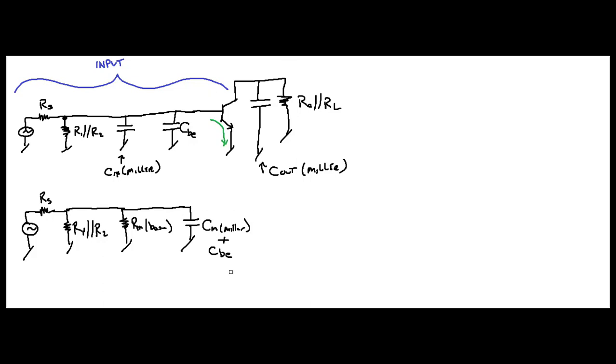All right. Now, let's take this. Let's Thevenize it. So if we Thevenize it, we're going to look from here this way, right? We're going to Thevenize this whole thing to get the Thevenin resistance.